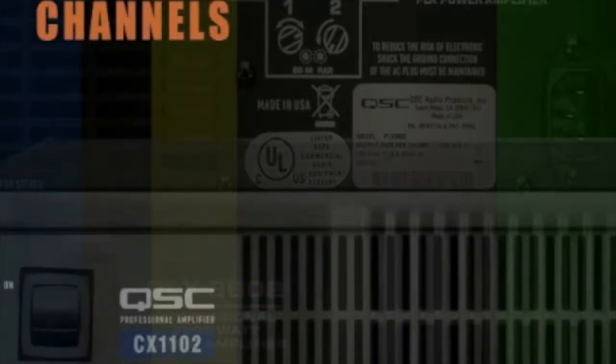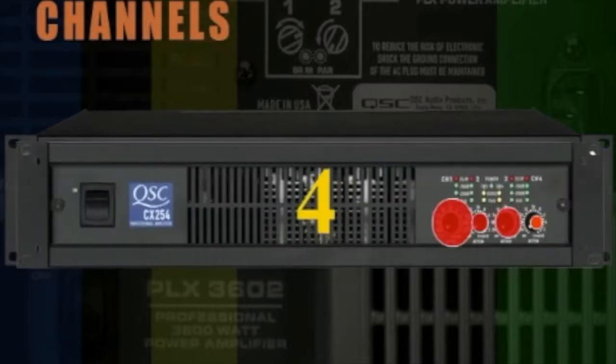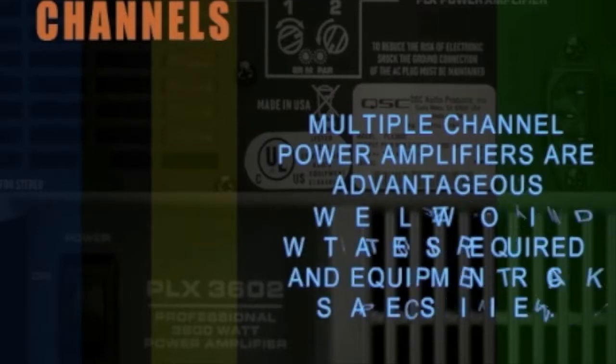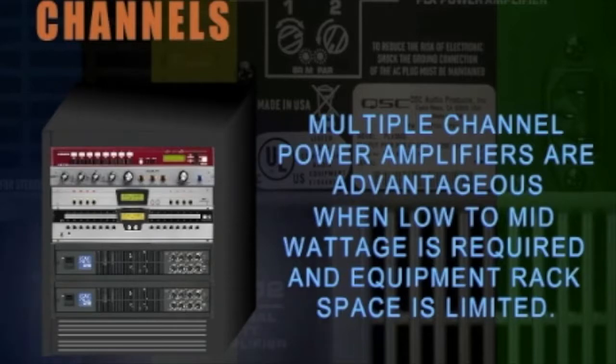Most power amplifiers are stereo, meaning they output 2 channels of audio. Amplifiers also come in multi-channel versions that have 4, 6, and even 8 output channels. Multiple-channel power amplifiers are advantageous when low to mid-wattage is required and equipment rack space is limited.